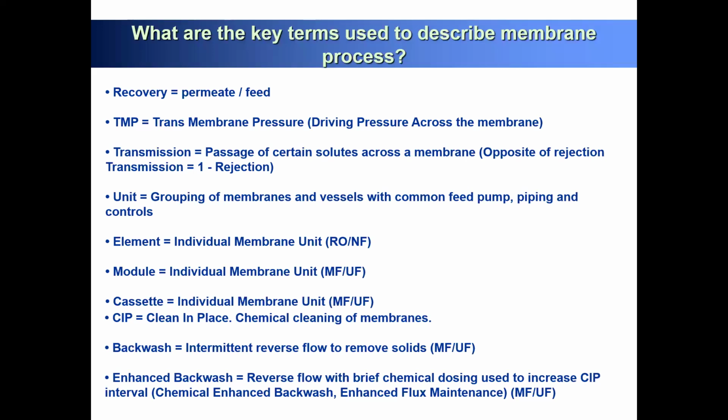So this software will tell you which compound passes through this membrane, other membrane, so they can provide the information, or you will get 0.1 milligram per liter of boron concentration. You will get 100 milligram per liter of total dissolved solids. So all the information is available from our software.